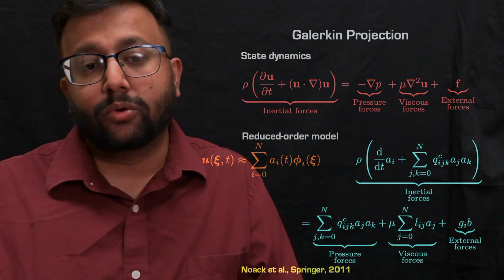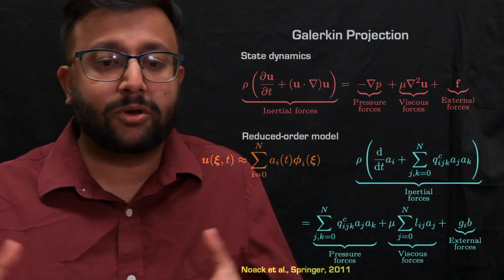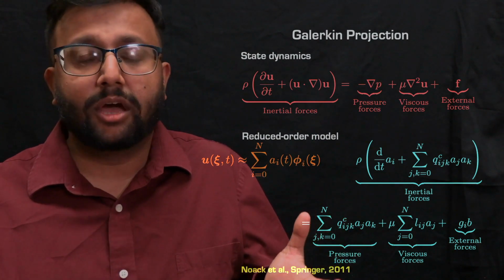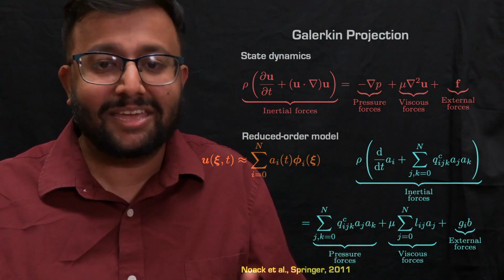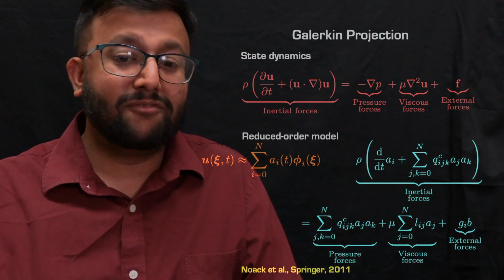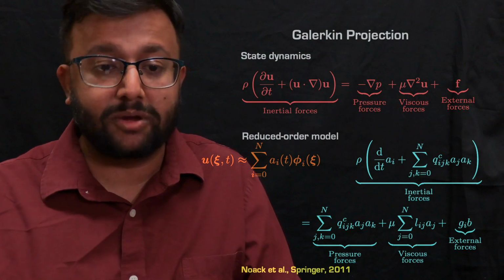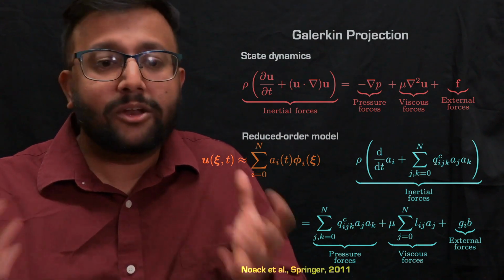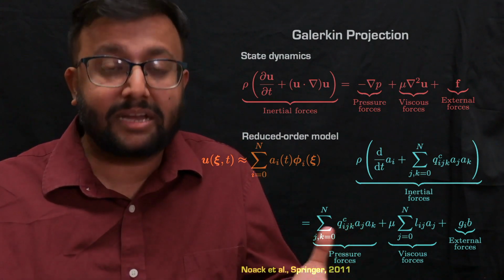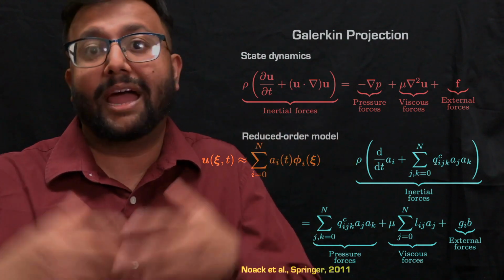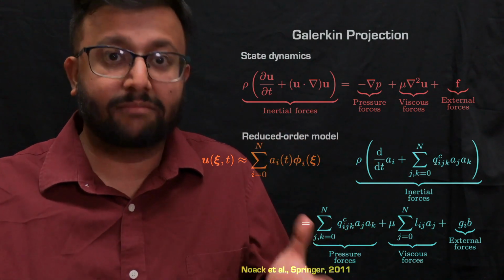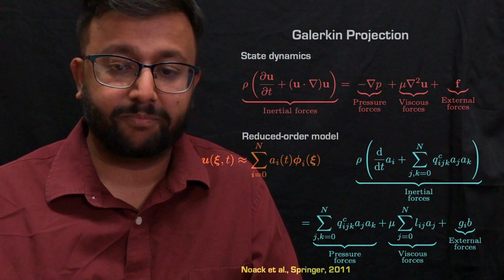That's the same as, because the time averaged flow does not have any time varying component to it, we can fix that coefficient to be unity. This way, I do not have to track the mean separately from all the modes of the flow while constructing the Galerkin projection reduced order model.